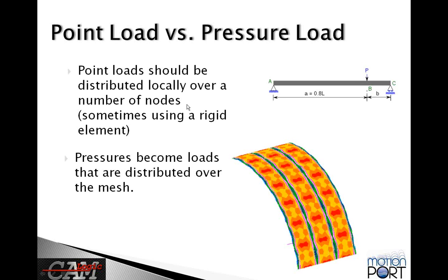And that actually can become quite a natural thing to do, because if you think about a connection between components where you might have that concentrated load occurring at the joint, usually in that location you have some kind of hole, where there's a pin, and then kind of a collar. So the actual force is being distributed around the circumference of the hole.